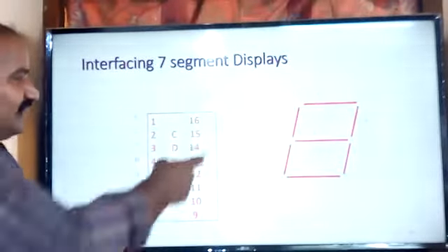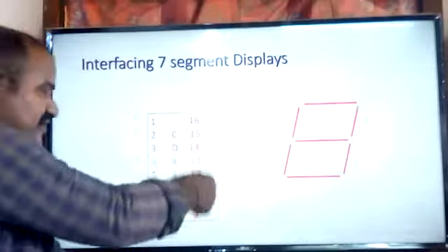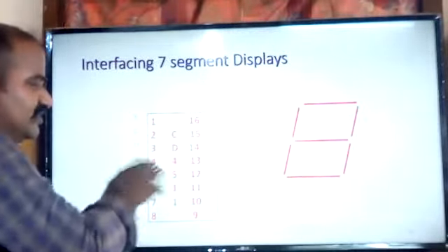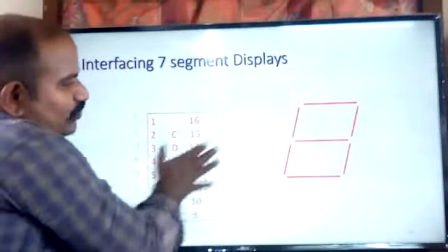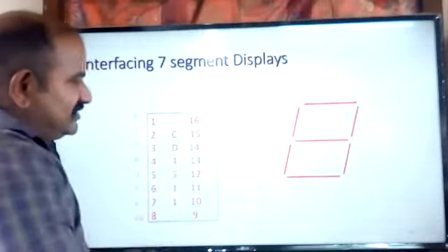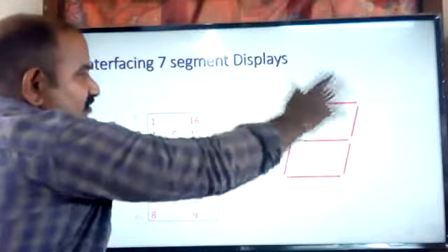After that, we have VDD and VSS, which are the power supply signals, and these are the output lines. That is a 7-bit output coming from the CD4511. Based on the naming of the A, B, C, D signals and the outputs, we are going to interface this output block to the 7-segment display.